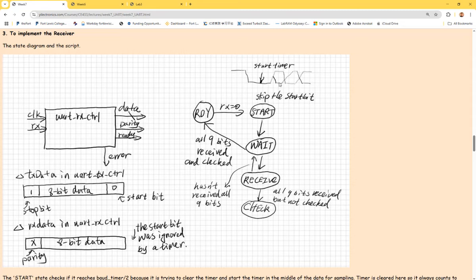So in that case, imagine you have D flip-flops in the receiver. When you want to trigger that D flip-flop to latch that bit on the line to the register, when should you sample it? In the middle, at the edge, after it, before it? In the middle, right? So in the middle will be the most stable state.